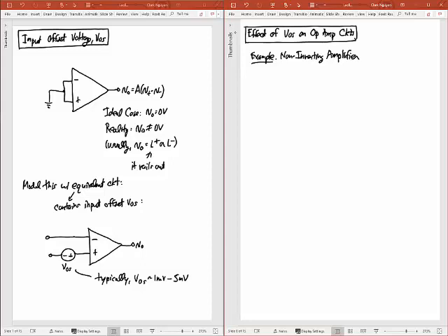Okay, so you know this circuit. I'm basically going to take an op-amp, and if I put the plus terminal here, the minus terminal here, then a non-inverting amplifier would take a resistor here to ground. Call that my R1. It'll take a resistor here in feedback from the negative terminal to the output terminal, V0, and then from the plus terminal is where I would want to ground this terminal.